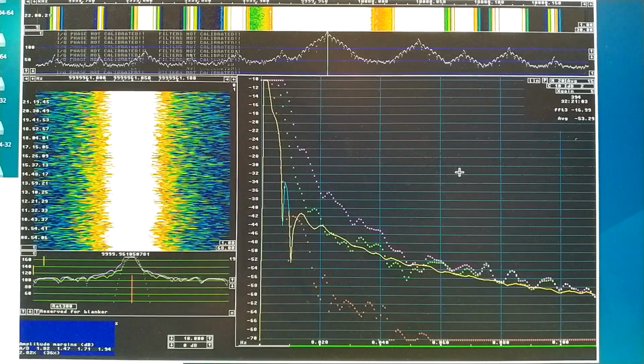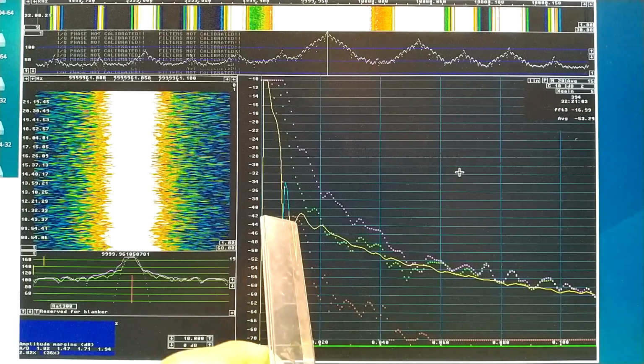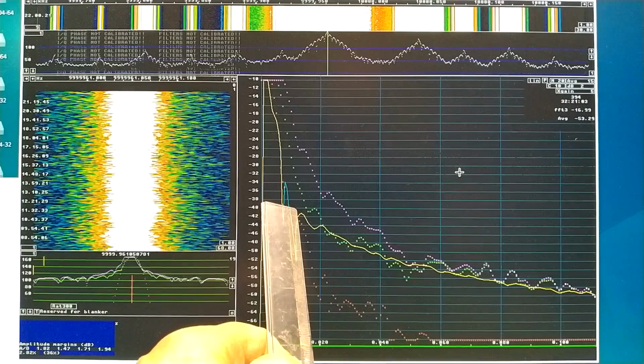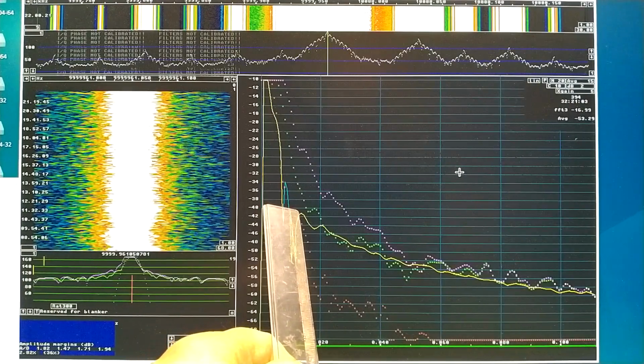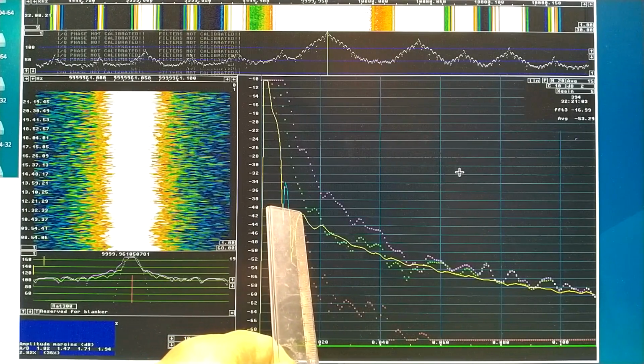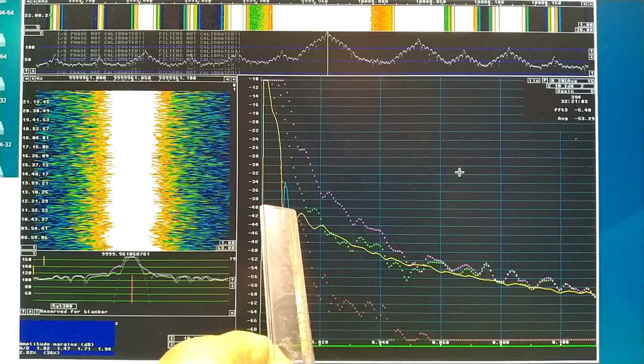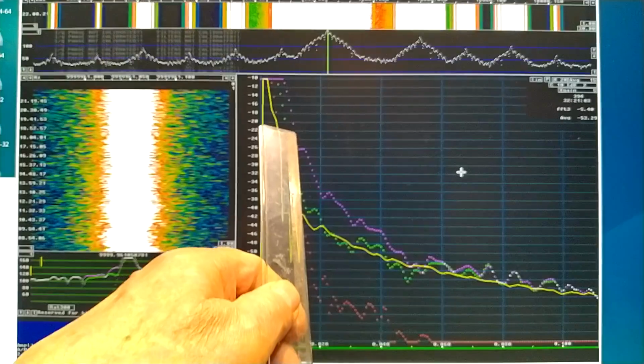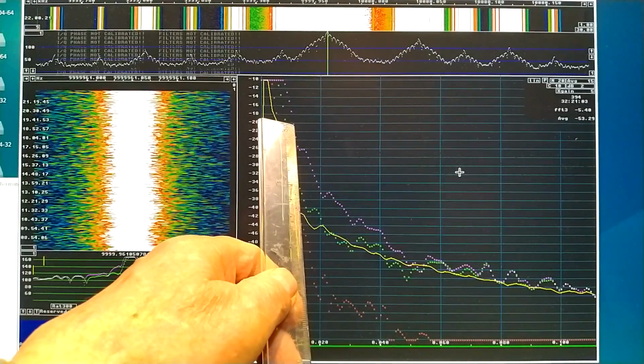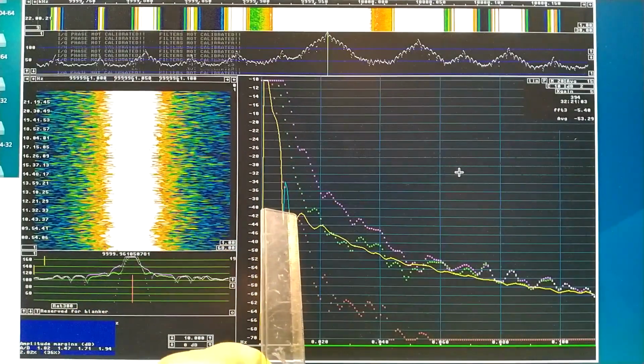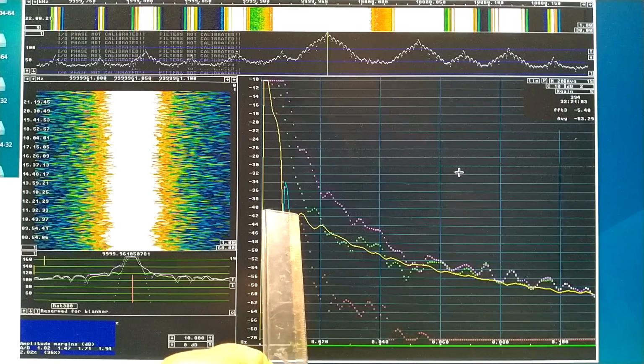Here is what it looks like in a linear frequency scale. Down to 0.1 Hz the measurement is reliable, although the yellow curve is not reliable because the statistics is not good enough. These are only 394 averages, and channel 2 is at minus 20 decibels, while the rubidium is at minus 40 approximately.